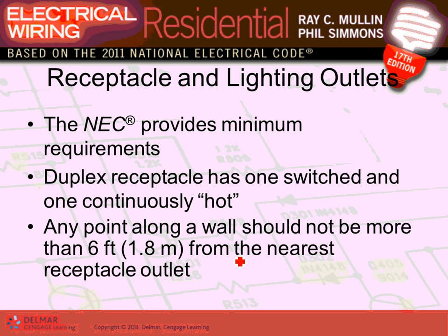Okay, so these are your branch circuits. Now, knowing this, Karen, my friend, and Derek, hopefully you can take this and start circuiting your kitchen. When you guys circuit the kitchen for me, starting this week or next week, you're going to be using these rules. Okay, double receptacle has 1 switched and 1 hot.